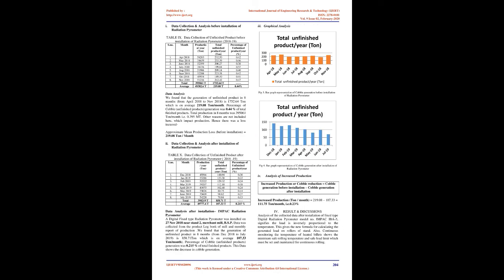There is a moderate negative linear relationship between load of rollers, L, and temperature of heating zone, Th, i.e. minus 0.302. According to regression coefficient table, we can formulate the formula for the relationship between load of rollers, L, in term of temperature of billet at stand 2, Ts, and temperature of heating zone, Th.